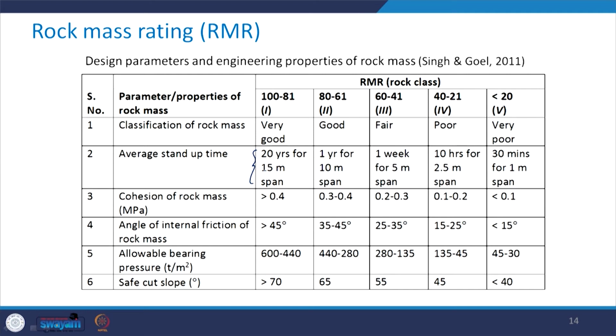Obviously, in case you have very good rock mass, you may have a very nominal requirement for the support system. This installation of the support system becomes quite crucial if you have fair, poor or very poor quality rock mass, because you can see that here it is 1 week for 5 meter span, 10 hours for 2.5 meter span, and here it is only 30 minutes for 1 meter span.